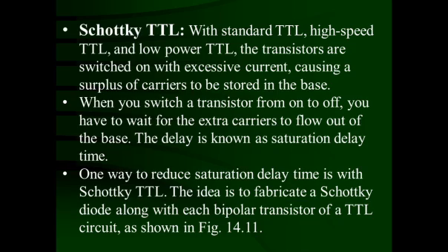So with these three main types of TTL, that means standard TTL, high speed TTL and low power TTL, the transistor goes into hard saturation because of very high, excessive currents when the transistor is conducting. That means extra charge carriers are situated inside the base, and when this transistor goes from on to off, then these extra carriers have to come out from the base, and this requires a little more time. This is called saturation delay time.